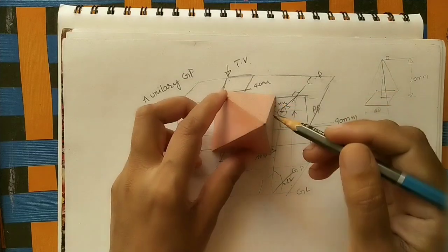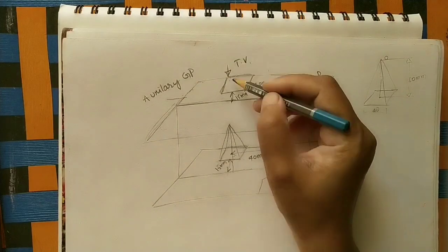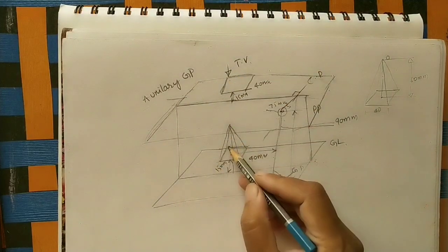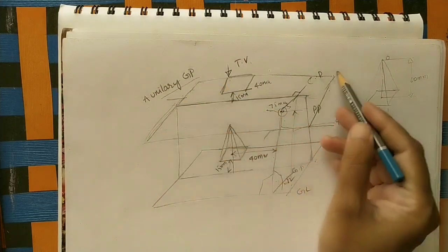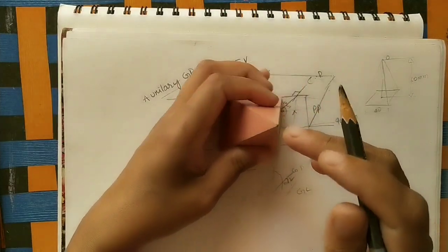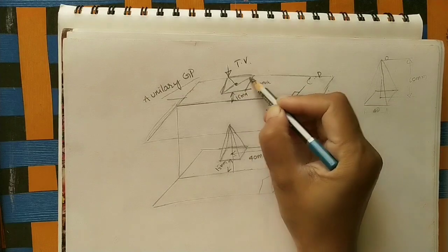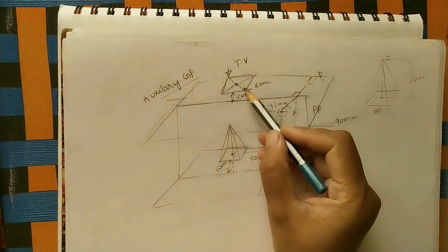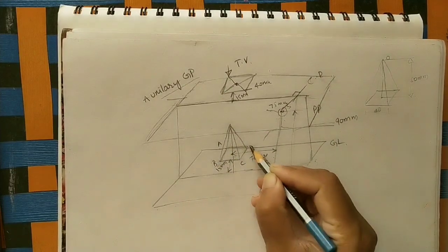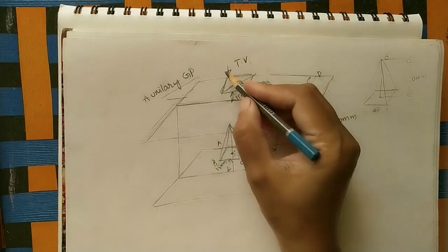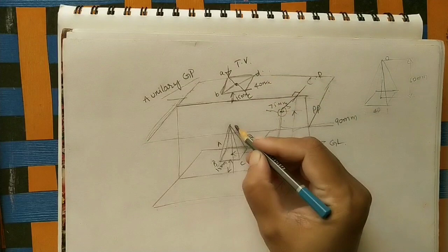And then after the square, we can see these edges also, all meeting at the center. So whatever top view we are taking, we will see initially this base. I will draw this base on this auxiliary ground plane. This is also a transparent plane, so we are seeing this top view, and also we can see these edges, all meeting at the center like this. This is the center of it. This is the top view we are getting for this square pyramid. Mark the names. This point I am giving capital A, B, C, D like that. So in the top view we will mark the small letters. A here, this point is B, and C, this is D, and take the apex as capital O.